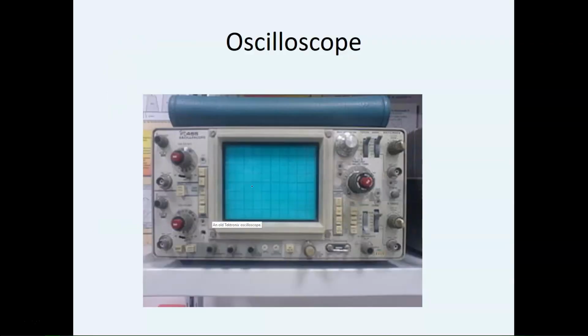This is an oscilloscope. So what you would see if you turn this on, if you look at it for DC, I'm sorry, I cannot draw. What you should see for DC is a single straight line. You have to excuse me, I can't really draw with a mouse. If you were looking at a signal for AC, however, what you should see would be a sine wave. And the way you would clarify it is using these different dials to dial in on what you're trying to look at and how you want it to be viewed. It's something, like I said, you'll use heavily in AC.